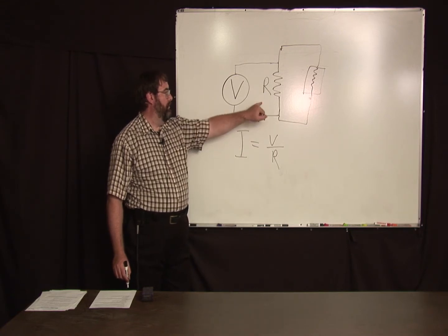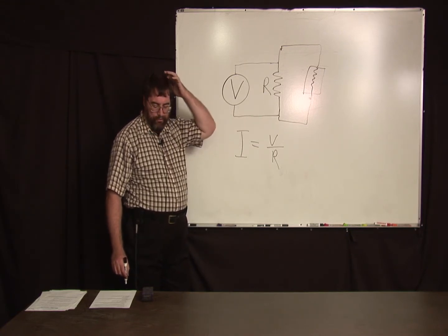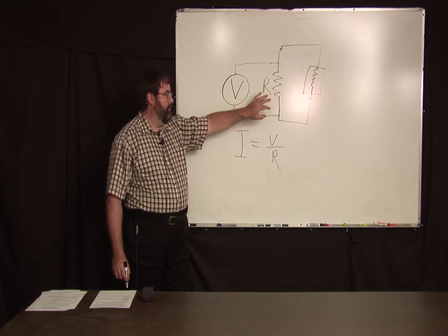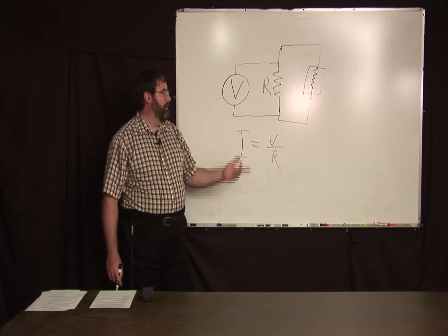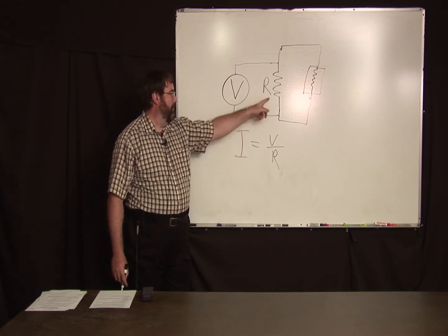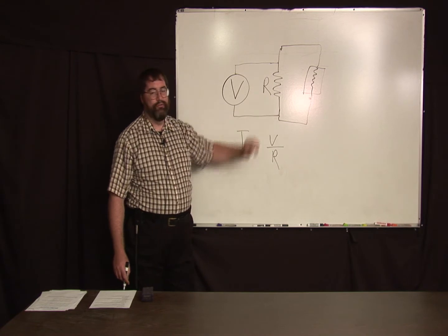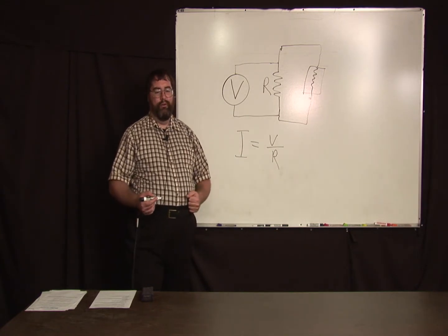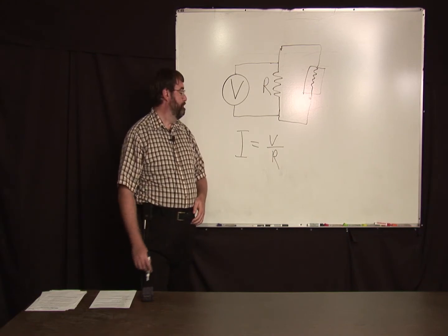You can actually figure out what the effect is, because you know what the voltage is and you know the additional resistance in the circuit, so you can see how that will reduce the current based on what you think it is. So the error is you have to introduce a small resistance, which according to Ohm's law will change the voltage slightly.